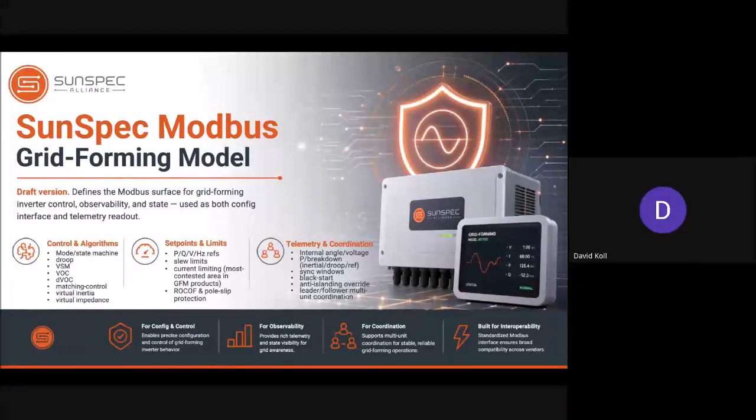Our working group has a lot of experience with grid following devices. We're looking for help from people with experience with grid forming devices. We need help from people with a basic understanding of the concepts that differentiate following from forming. Concepts like droop control, island mode operation, intentional islanding, microgrid operation versus anti-islanding, virtual synchronous machines, virtual oscillator controls, pull slip, states of grid forming, synchronization, etc.